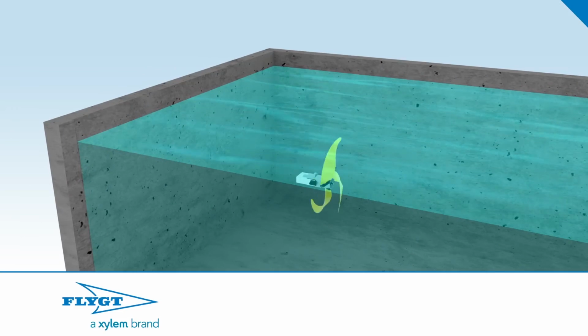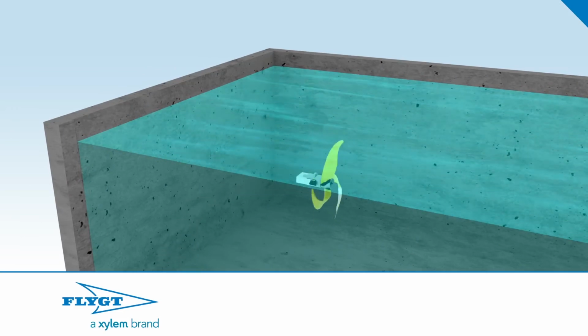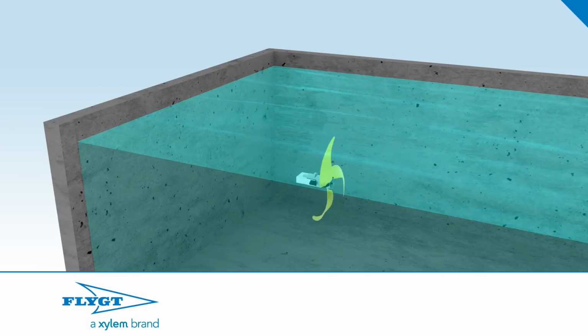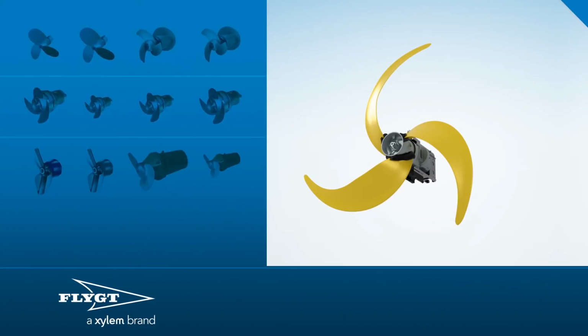The 4320 can also tell if rags are building up on the mixer blades. The motor's integral speed control senses the excessive load and automatically backs off on the speed so the materials will fall off. Then it returns to normal operation without any need for human intervention. Finally, the 4320 can dramatically reduce inventory costs. Many wastewater treatment plants stock a number of different mixers because their various applications need different amounts of thrust. With the 4320, a single mixer can replace a dozen different size mixers.